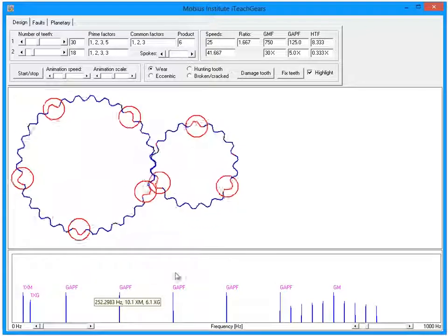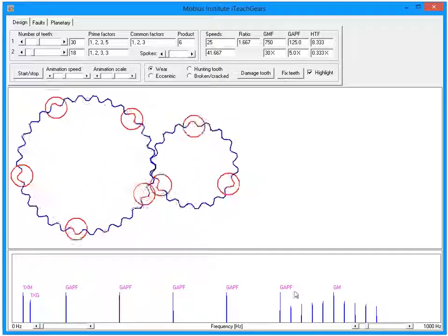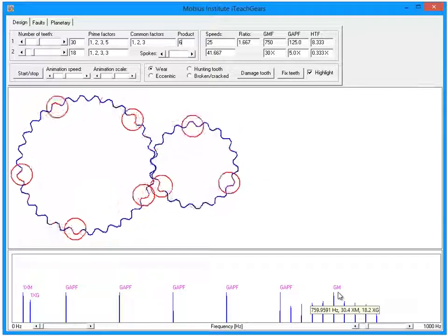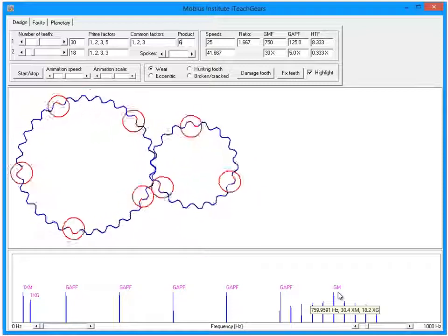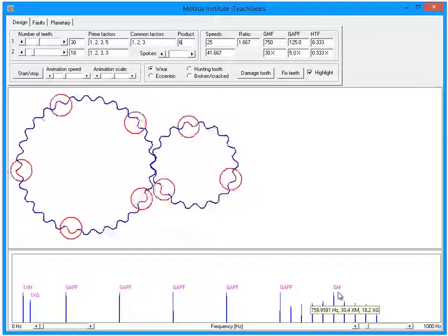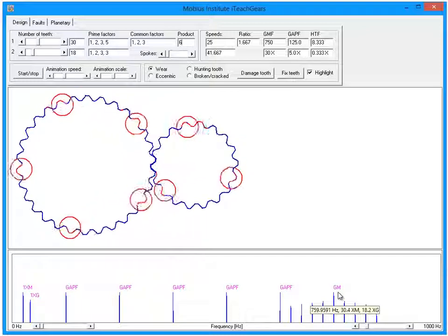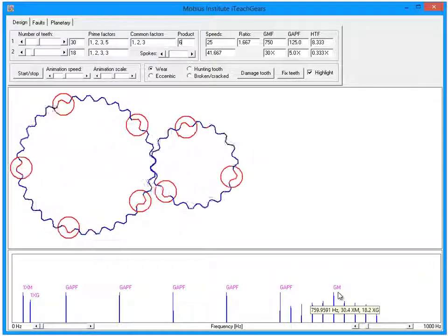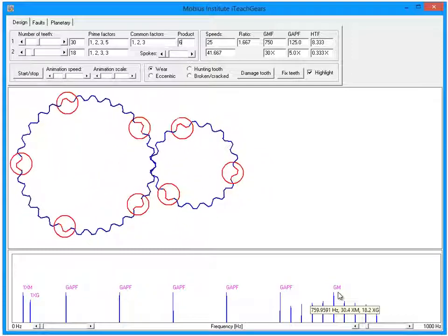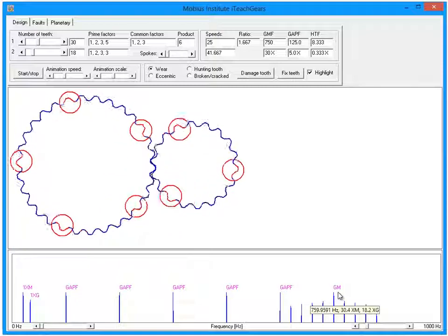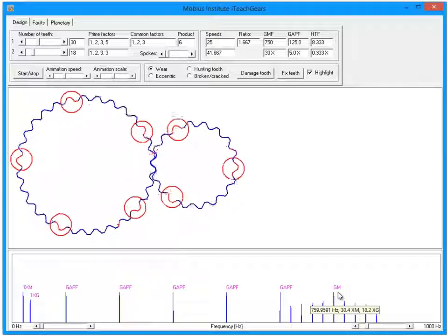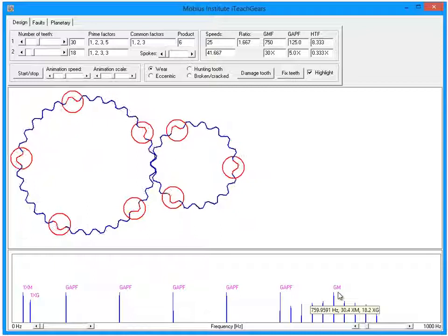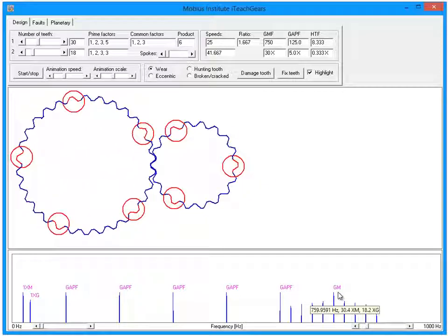And so our gear mesh frequency divided by 6 is this. And we've got harmonics of it. Of course, there's 6 harmonics: 1, 2, 3, 4, 5, 6. Anyway, all the math works out. The point is you can see these peaks. Now, as I said, ideally a gearbox will be designed with a prime number of teeth. But if there's a specific design that was required, there may not be a combination possible with prime numbers. So they have to use these non-prime numbers of teeth, and therefore this is a source of vibration that you may see.